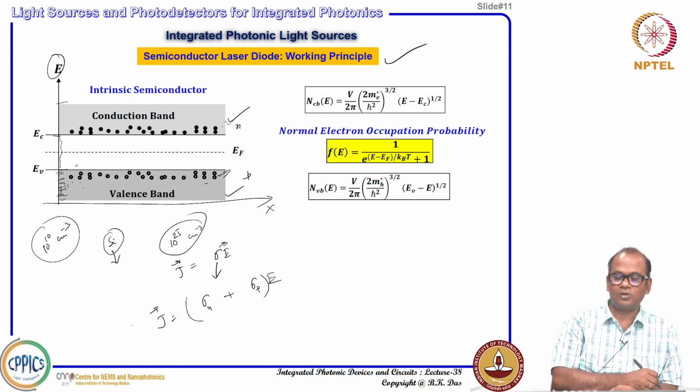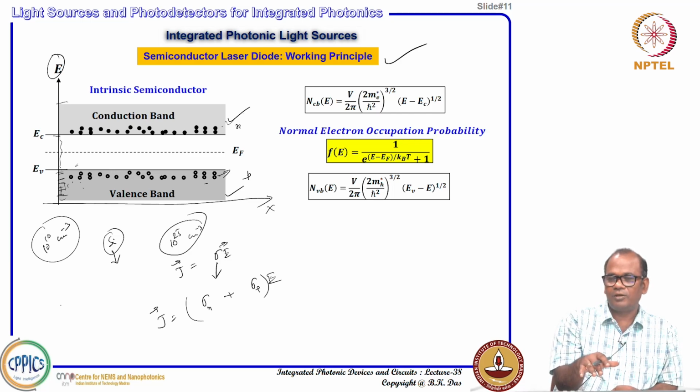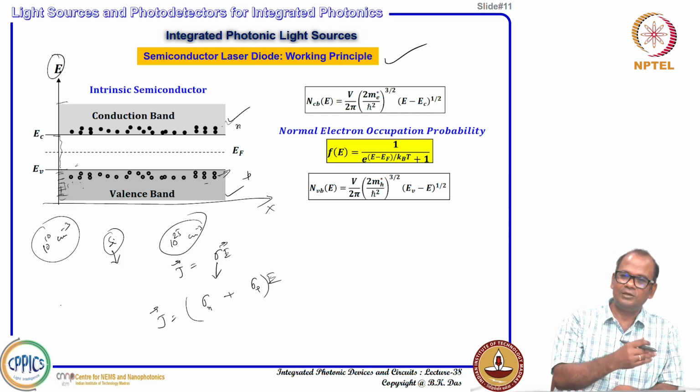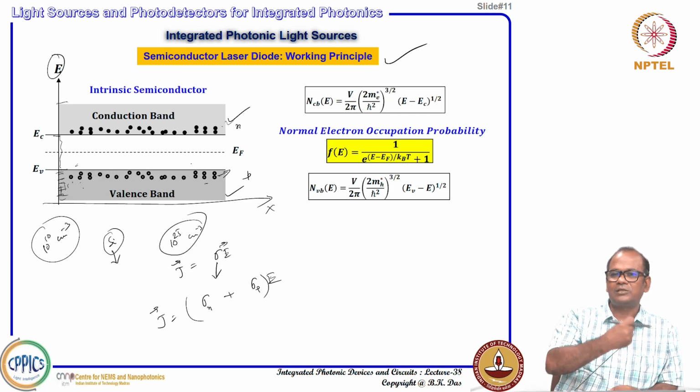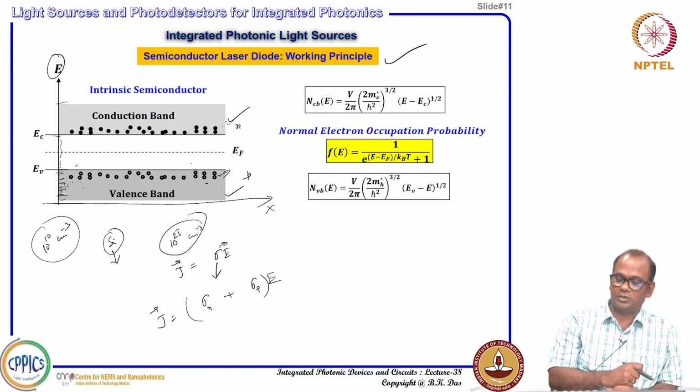But in case of a conductor, normally you do not have such a situation. You have only the highest band, and you will see that it is not completely filled. So, some empty energy levels are there. That is the reason the highest band, that means this conduction band itself, has some empty spots; a lot of energy levels are free. So, if you apply energy, an electron can acquire some energy and become mobile, and it can have good conductivity.